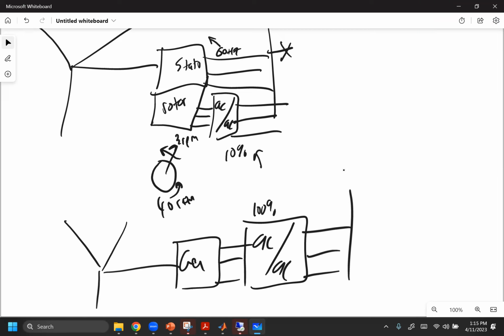The generator has, because you have the very, very low output RPM, and you want to get high frequencies for control, you have a permanent magnet rotor, and then there's somehow another permanent magnet rotor around that one, and then a stator winding, and it creates an artificially larger number of poles. It's a very weird technology.